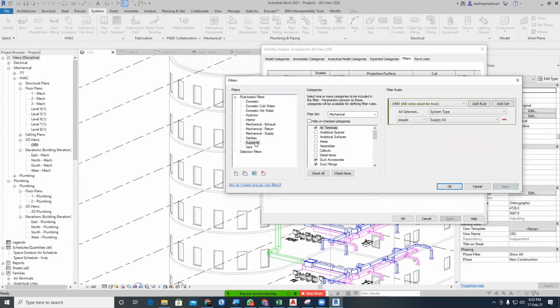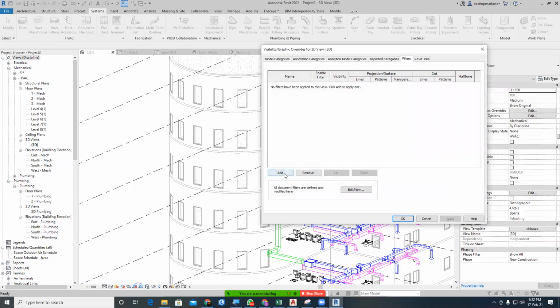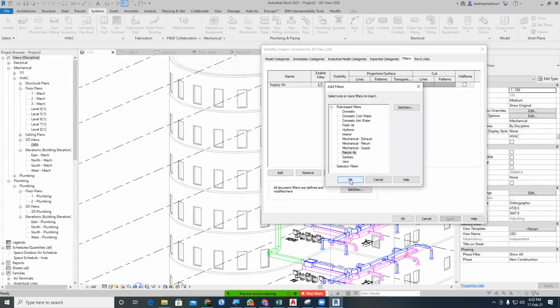Okay. So one is created, so you don't have to create again. Just duplicate it, one and one more. So this one you rename. Let me go with return. Then I can just make it return from here. And then here you have this one, and let me make it fresh here. Fresh. I can go with okay. Now you can go with add. I want to add supply, add the return air, and add the pressure connection.